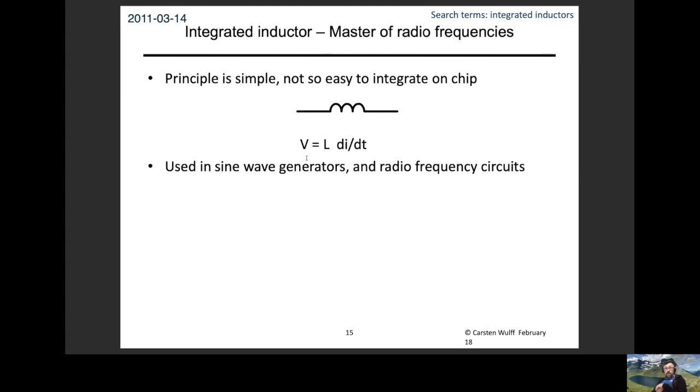But the parasitic inductors, so every single metal wire you put down on the chip, will have an inductance. For example, yes, you can draw amperes of current into an integrated circuit, but you need to think about the nanohenry inductance in the bond wire, the wire that goes from the chip to the package. If you don't, you might actually destroy your circuit, because if you're pulsing that amp current, it can ring like crazy and cause damage. And I've seen that.